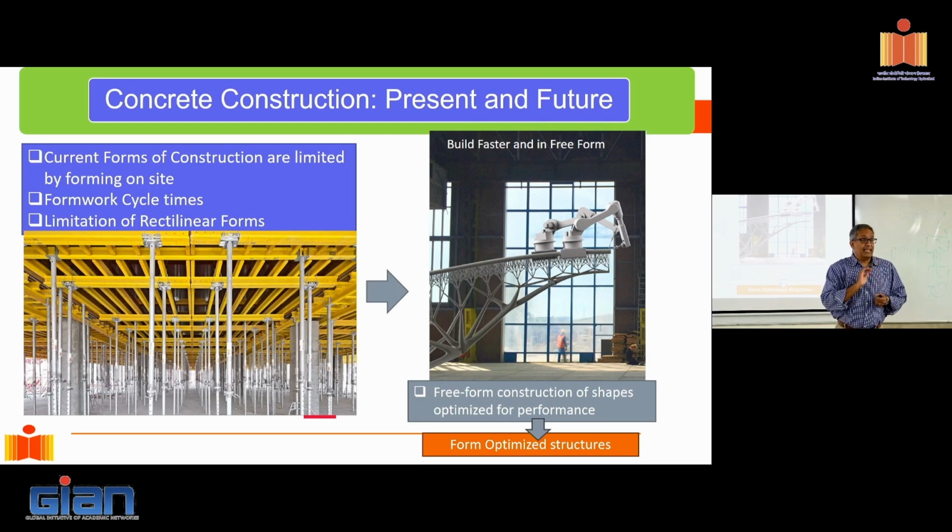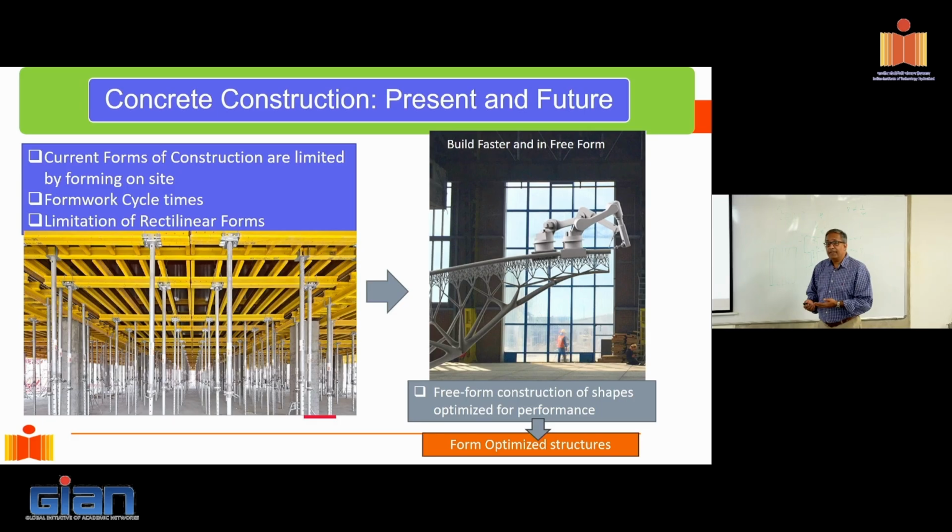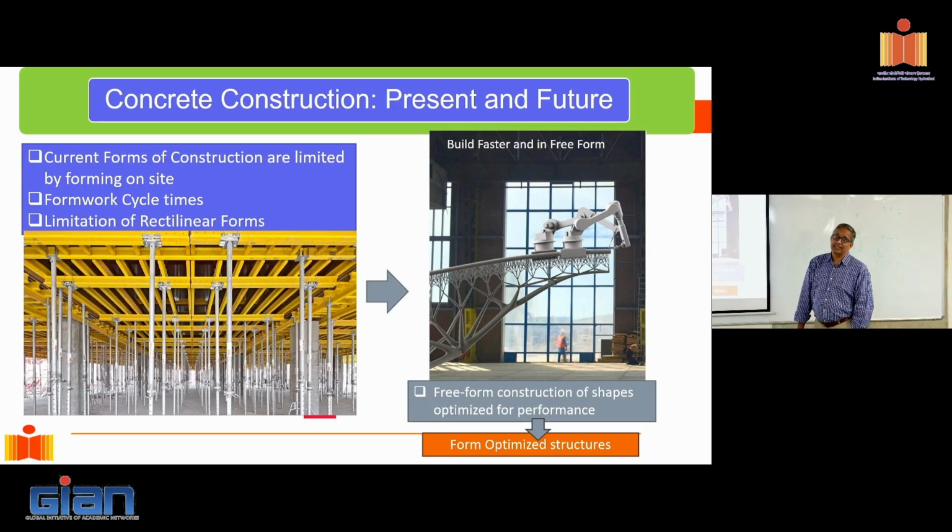And here what I would say is, look, if you want to go longer in span, take away material, don't add material to it. Okay, it may seem very counterintuitive, right? But then what am I doing? I'm basically reducing the demand that I get from the dead load itself, the self weight. Okay, a very counterintuitive design proposition. And that's what we need to work on if we are going to make 3D concrete printing successful.